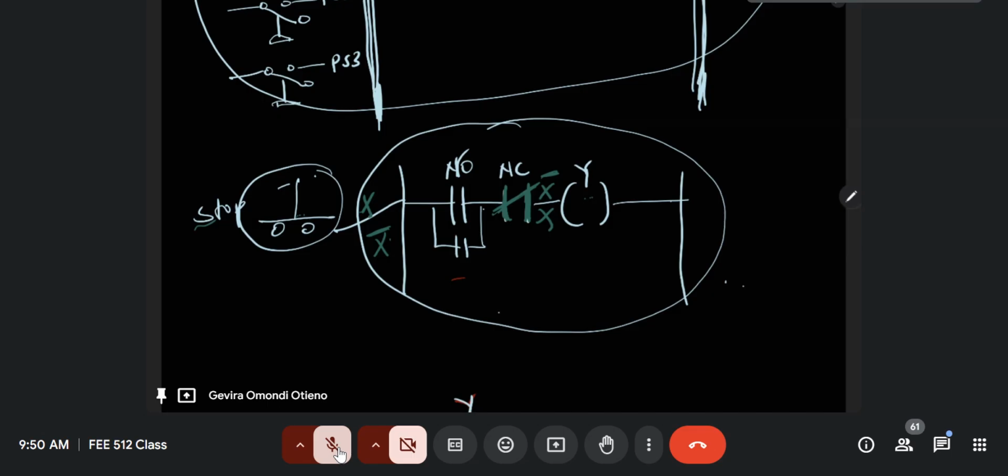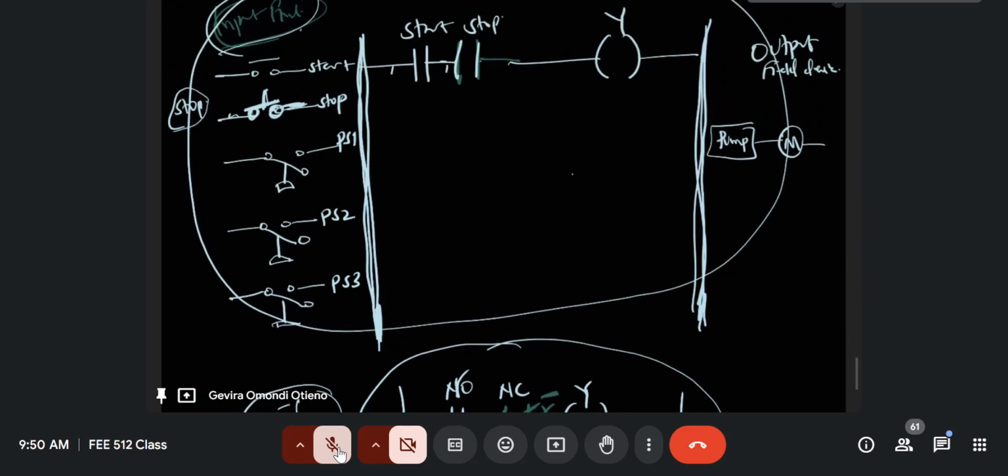So I'll repeat this for the last time, and I have 10 minutes, so we might not complete this, but it doesn't matter. If you were to incorporate input field devices, it is understood naturally, internationally, and by engineers that a stop push button comes as a normally closed contact. That's why we call the PLC wiring for a stop button normally closed.